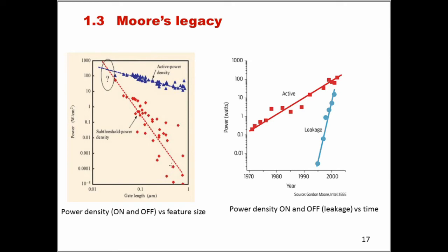Now, what happens is that as you shrink the device, you have to shrink everything. You shrink the channel, you shrink also the gate oxide. And so this drives to leaks that can go through the gate oxide, can go through the channel, and so overall, as you shrink the device, so here the gate length is decreased, and so imagine that if we start shrinking the device, we are moving in this direction on this axis.